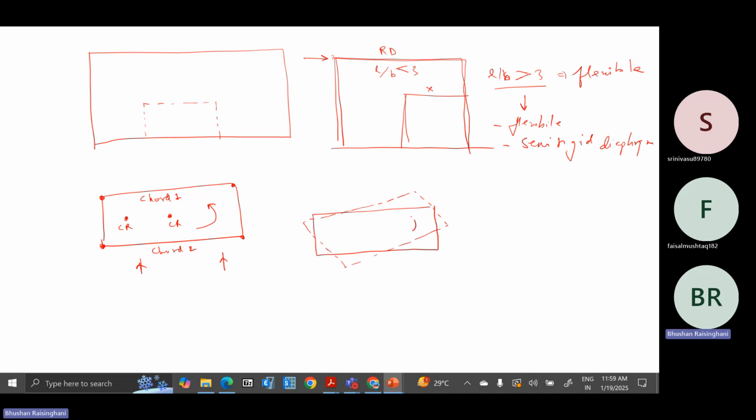As the building is flexible in this direction, so from this 0 point you can see the deflection. This is the radian theta they are estimating, or the deflection they are estimating from this value. So they are using the deformation up to this level, not end to end. Okay, so they have a ratio theta max upon theta average.